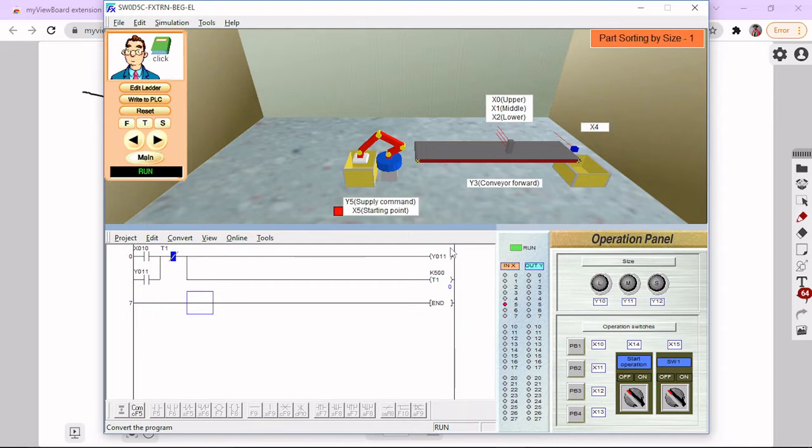So we can see that once K500 has been reached, the lamp went out because the contact here, X10, is a push button which has gone de-energized after the button has been released. So although the P1 is a normally closed contact, energized, waiting for current to flow, no current is flowing, unlike the other time when we have it as a switch, which this one was X14. So that's why the other time it was just flashing, but now that's gone off.